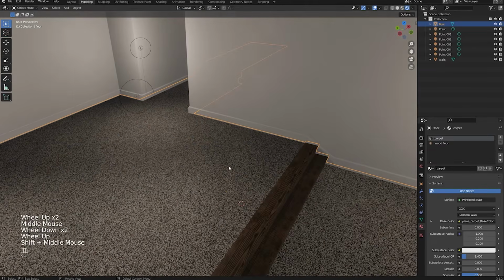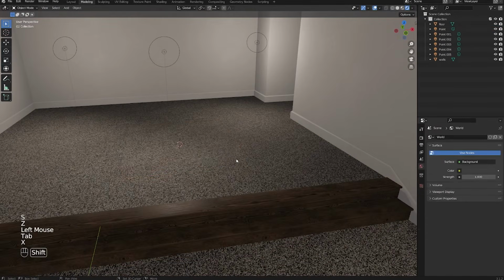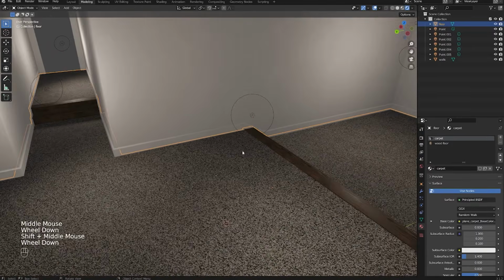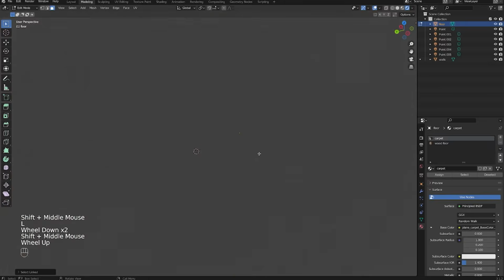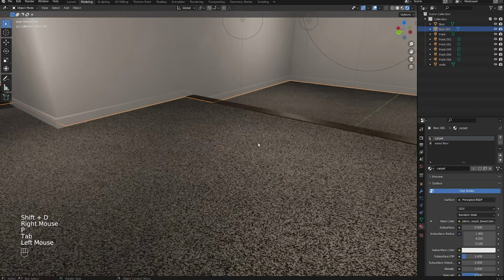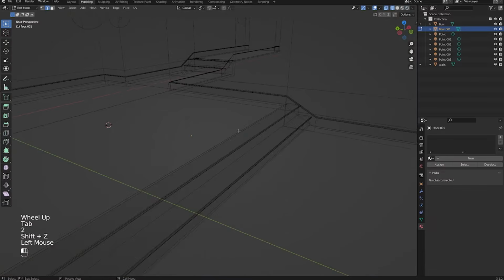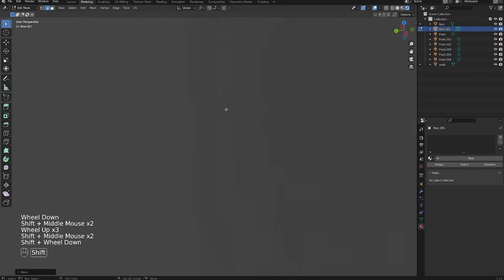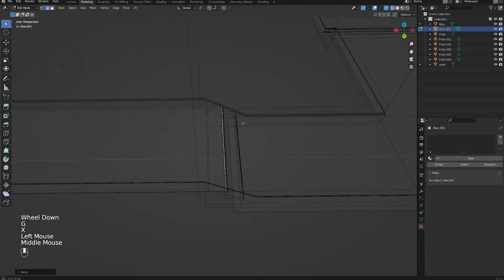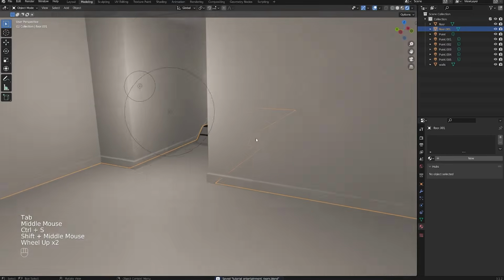one method I like to use is I like to go into Blender. I will manually create my own mesh for collision. So let's say for this floor, maybe I would take these parts, I would duplicate them, make it its own object. They don't need any material, so I would get rid of that, and then maybe I would take this, drag it out, do that for the stairs, and then do the same thing here, drag it out. Now I'm going really quick here, and this is kind of just so that you know.